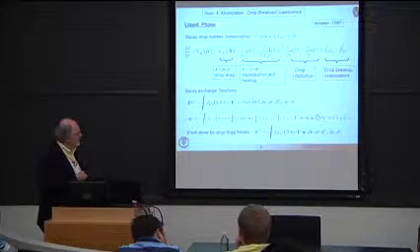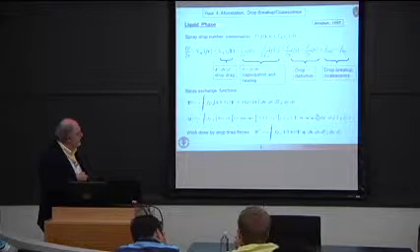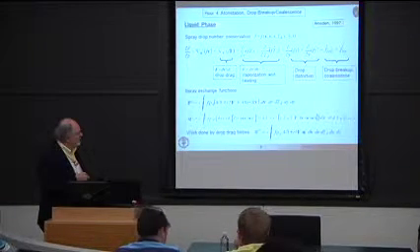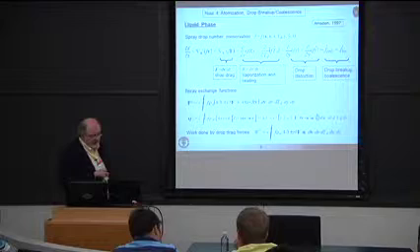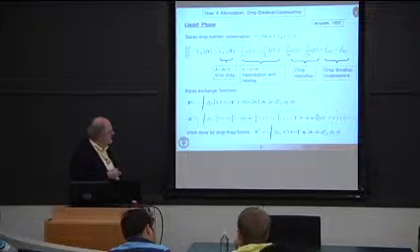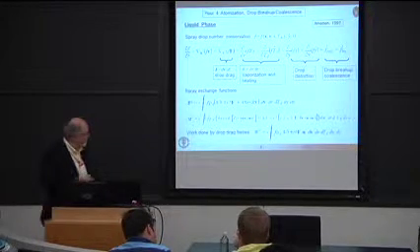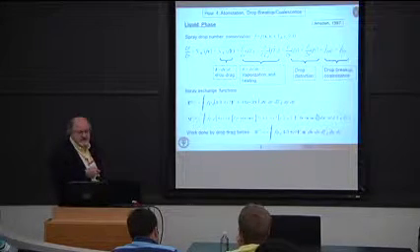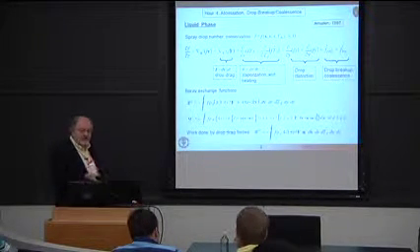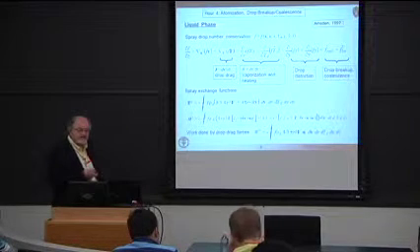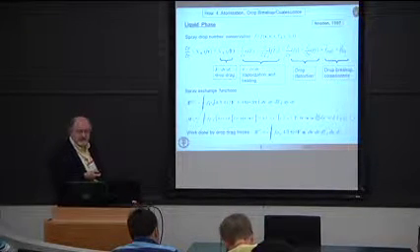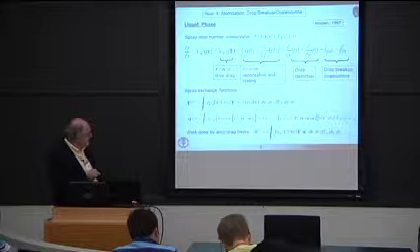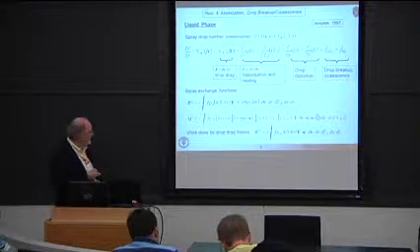If you look at the drag component, we have a term that is associated with the momentum exchange between the drop and the gas. But then we also have this term here. So as a droplet vaporizes, it is also adding momentum to the gas because that vapor leaving the droplet is a source of momentum for the gas. So we have to account for that in the momentum source term.